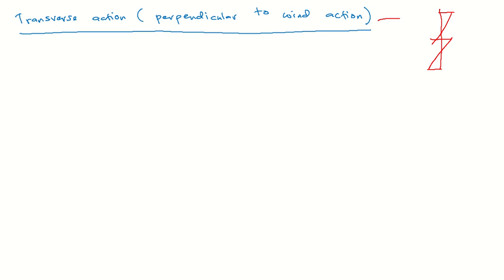Okay, this is what we want to find out for transverse action. And to get this manually, we can use the subframe analysis. If you remember in structure design, there's a chapter, chapter 2 or chapter 3, about frame analysis. Okay, frame analysis, we have 3 methods: complete subframe, subframe at a point, and what else, simplified subframe and simplified subframe at a point.